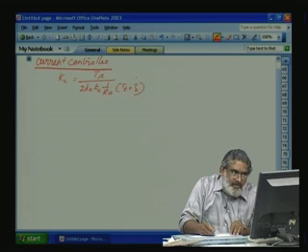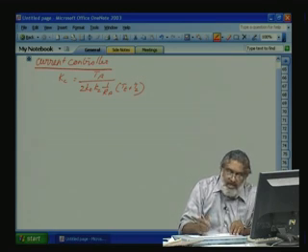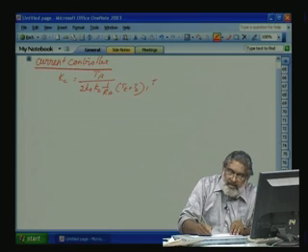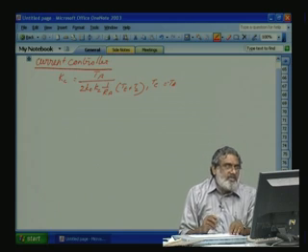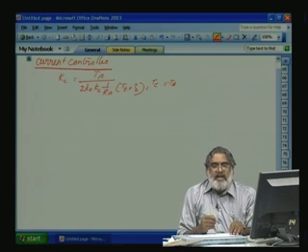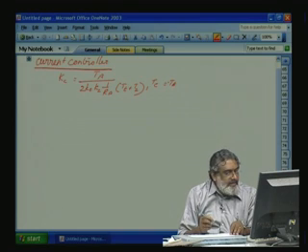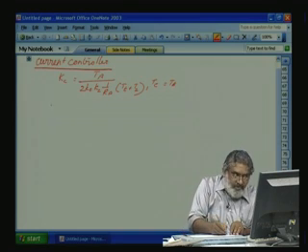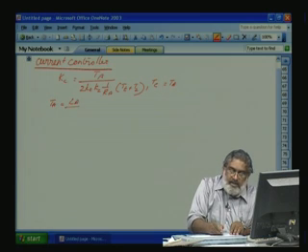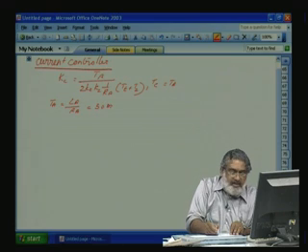This Tt is the converter lag, and T2 is the current filter time constant. And we know that Tc is equal to Ta, the armature time constant. So, we are using a pole zero cancellation there. Then we found the transfer function with theta equal to 1 by root 2. Now, what is Ta from the previous equation? Ta is equal to La by Ra, that is 30 millisecond.